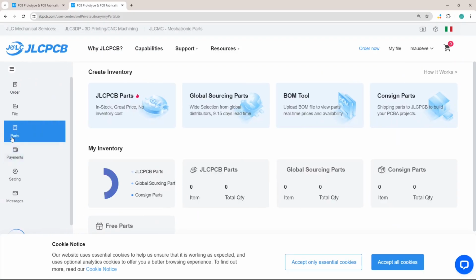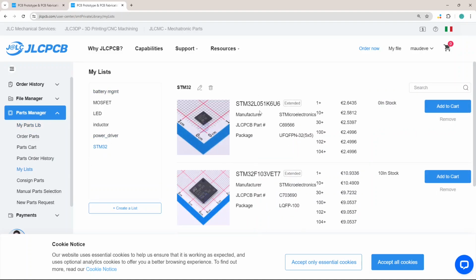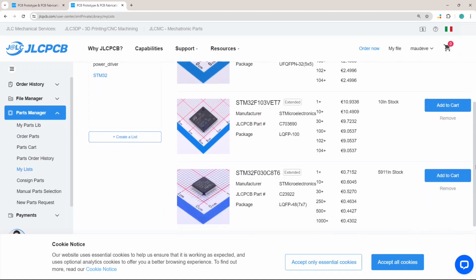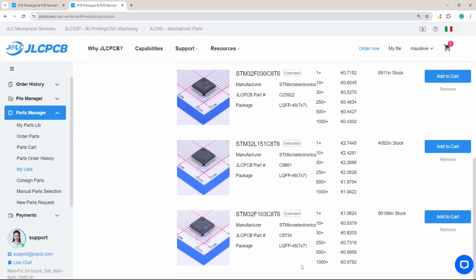That's why these two microcontrollers are in my personal part list. So, adopting an STM32L0 or L1, we have the advantage of an easier project design, not needing an external EEPROM, being also cheaper, taking advantage of the JLC PCB catalog developing the board.